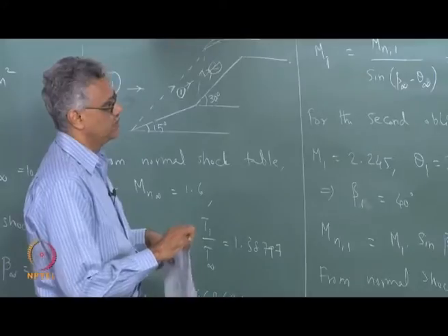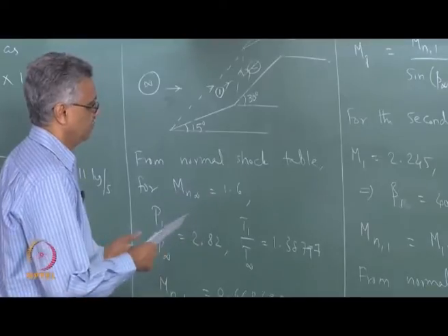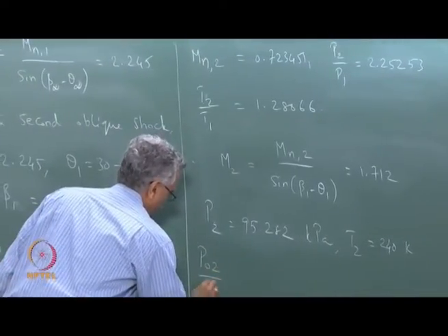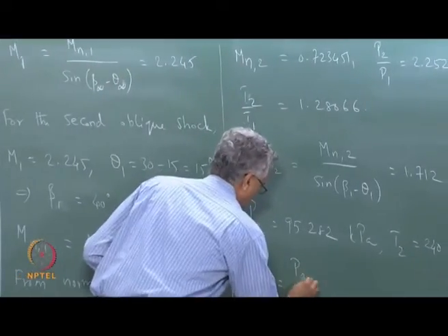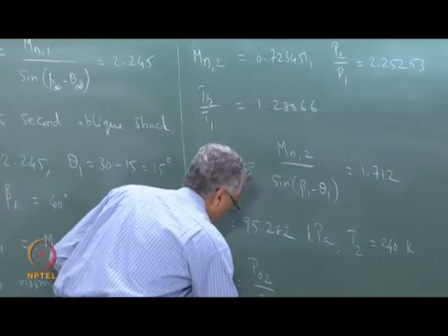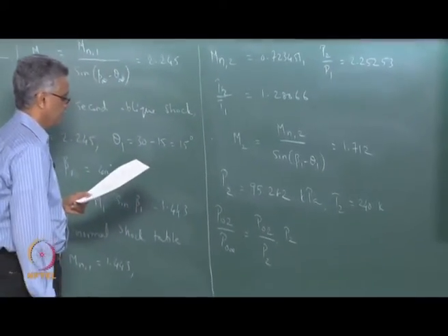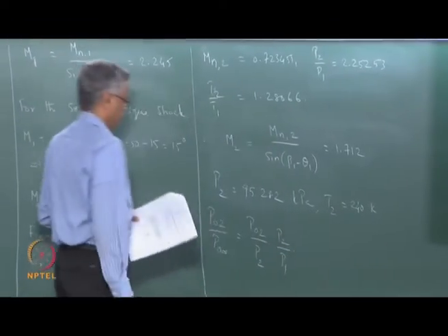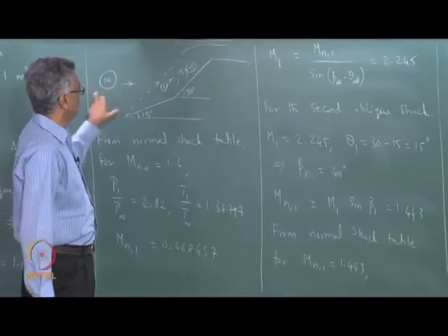We are also asked to calculate the pressure recovery at the end of the internal compression process. So we are looking for P02 over P0 infinity.